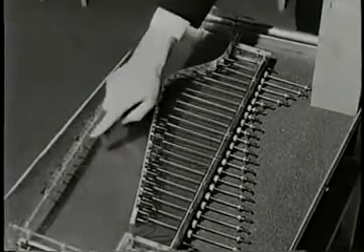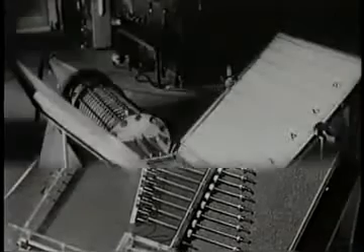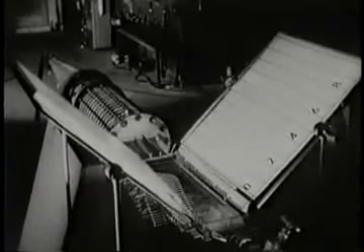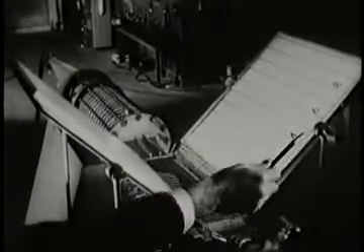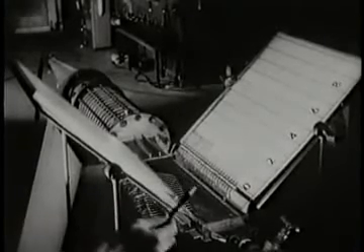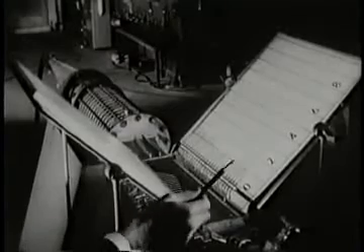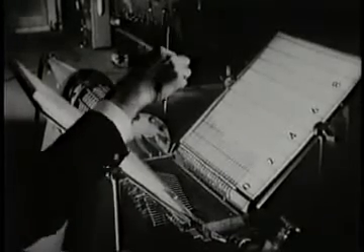A great many static pressure taps are in the straight wall and in the curved wall. Here it is set up for test. These are inclined manometer boards to show the pressure distributions on the two walls. We will observe the lengths of the water columns looking down from a position directly above.